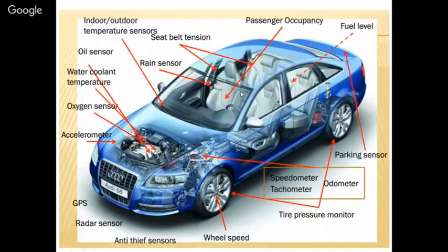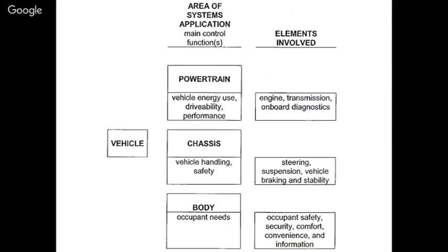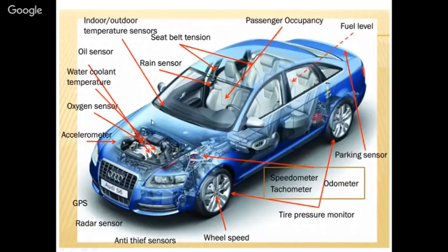But in many cars there are load cells or some kind of strain gauge sensors mounted under the seats, so that they monitor whether on the passenger seat a person is sitting. If somebody is sitting and the seat belt is not fastened, then again the car will give a signal that the passenger has not fastened a seat belt. So a seat belt tension sensor is there.